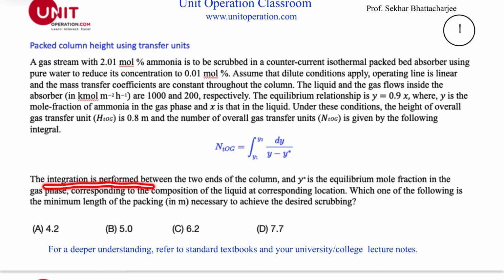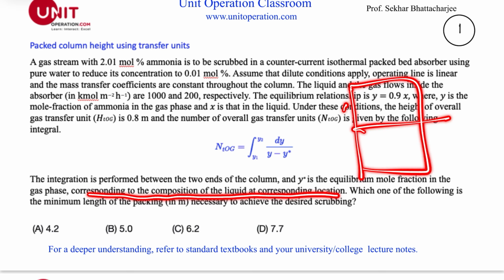The integration is performed between the two ends of the column, as we said, and Y star is the equilibrium mole fraction in the gas phase, corresponding to the composition of liquid at the corresponding location. As I've said, here at each level there might be some packings.